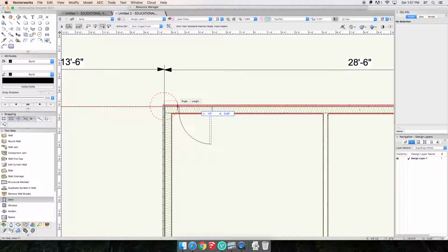So there I can see now I want it to be that from 1 foot from the corner of the sheathing to the outside of my door, and I can hit enter. Now what happens with that placed the door, but I still have my swing configuration to specify. Right. So I might want it to open in that direction, but I can see that it's going to place it over there, right? So I want it in this location, so I can pick either of those orientations.